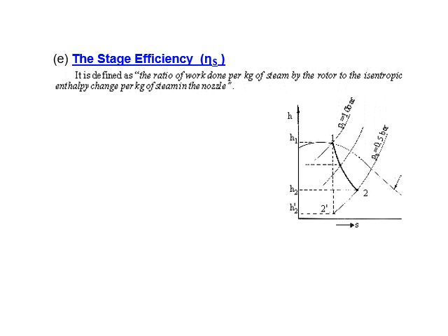Here the pressure is shown as 0.5 bar, and this curve 1 to 2 line shows the actual enthalpy drop, and the vertical dotted line shows the isentropic enthalpy drop, that is indicated by 1 to 2 dash. So now note down the corresponding enthalpy values for pressure P1 as well as the isentropic enthalpy drop position, that is H2 dash, as well as the actual enthalpy drop position, that is H2, on the HS diagram. So this one is measured from the Mollier chart.